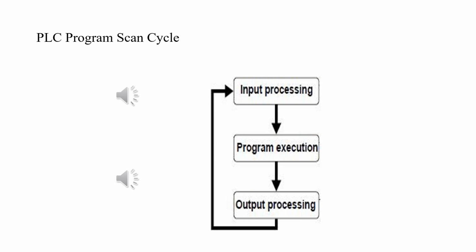After program execution, we go to the last phase of the program cycle, in which output status bits are copied to the output devices. If an output status bit contains 1, this means that the output device should be switched on. If an output status bit has 0, this means that the output device is switched off.